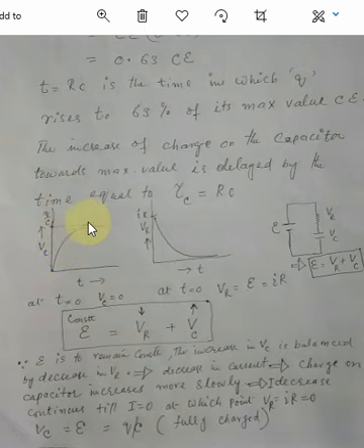The curve is bending, so it means that the increase in building up the charge on this capacitor is slowed down due to the decrease in the current. And finally, when it gets fully charged, the current will finally stop or will be reduced to 0.